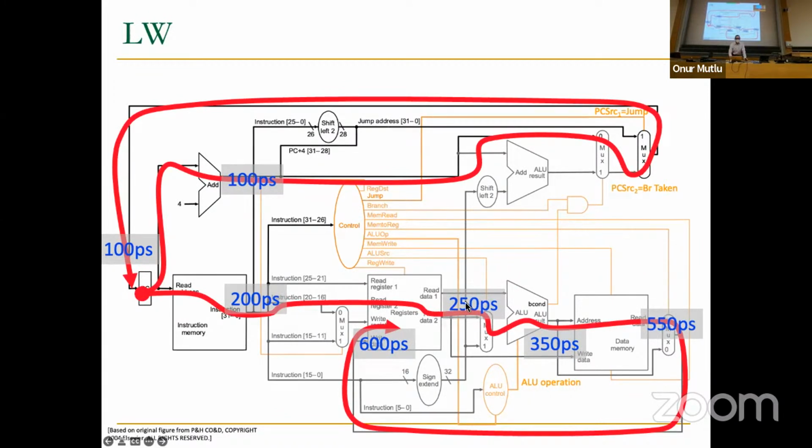One more comment over here. Why am I considering this other path? Because that could also potentially be the critical path, right? There could be multiple candidate critical paths, except this takes much longer than this part. And this is the concurrency in hardware, right? These things are happening concurrently. While you're doing this operation to get the registers, add them, calculate the address, access memory, and get the result into the register file, you're also incrementing the program counter.